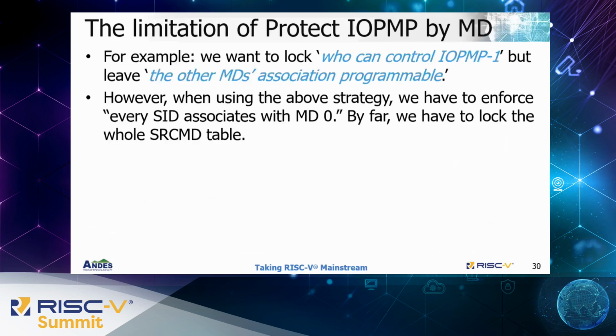If you want to keep the partial programmability of the SRCMD table like this example, locking who can control IOPMP1 but leaving the other MD associations programmable, we will quickly realize we are not able to lock only a few bits of those SRCMD registers by the above method. So we need a fine-grained lock.